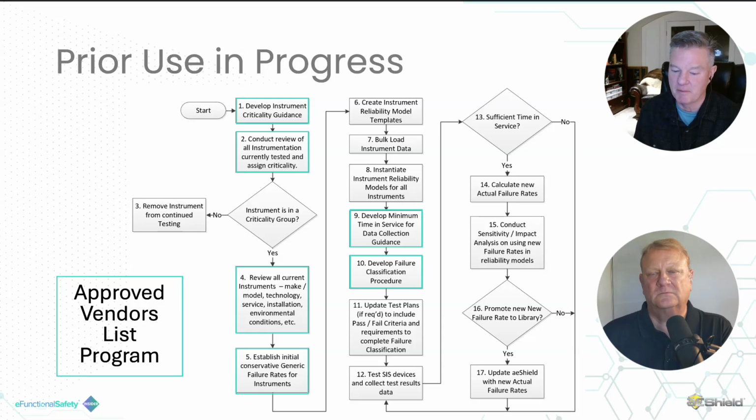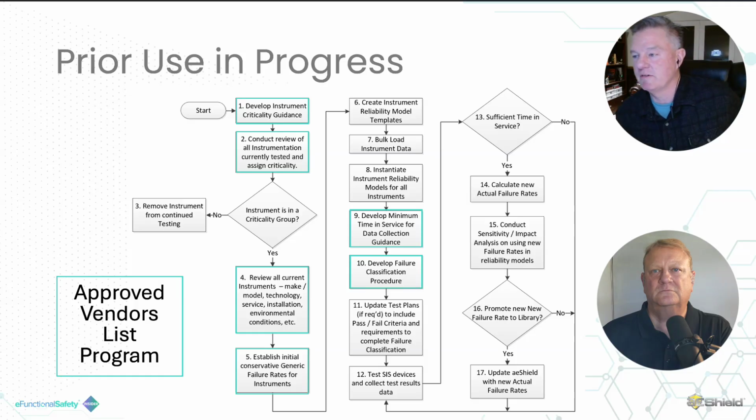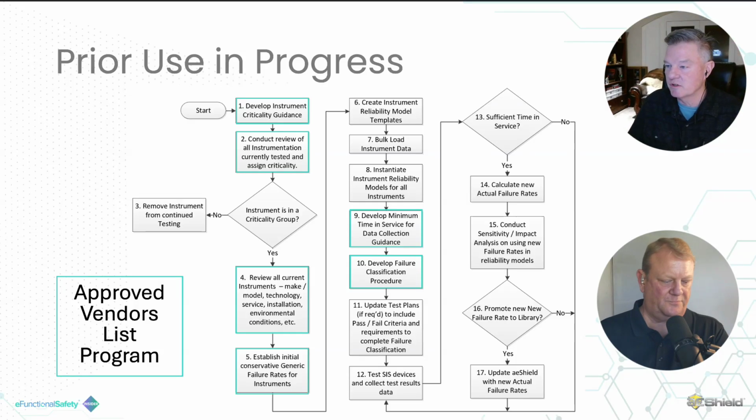I can easily buy a certified field device, a transmitter, right? Pressure, temperature, levels, flow, all those things generally exist. When we get into final elements, a lot of valves don't have SIL stickers. Motors, last I looked, you could get a SIL 3-rated motor contactor for like 25 horsepower. But if you have 250 horsepower, 2,500 horsepower, you're on your own. There are no SIL stickers on that stuff.